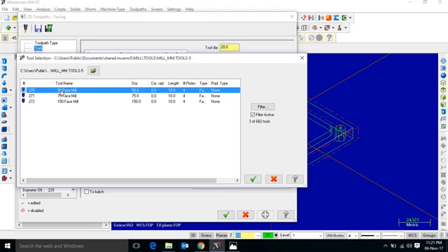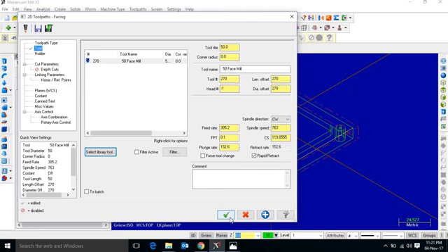After selecting the library, there is a facing tool. I have to do the facing operation, so we select a facing tool: 50 mm face wheel, 75 mm face wheel, or 150 mm. Select any tool. Now we are selecting the 50 face wheel, which has a diameter of 50 mm. Okay. After that, the tool that we have selected appears here. Depth of cut.